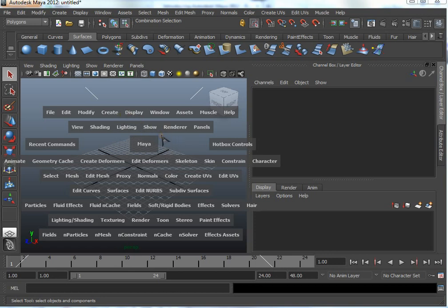Now if you activate the hotbox and click any of the zones, the north, center, east or west, it will show you a context menu of commands, also called the marking menu, which are related to that part of the hotbox menus.